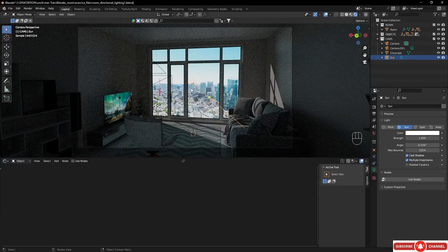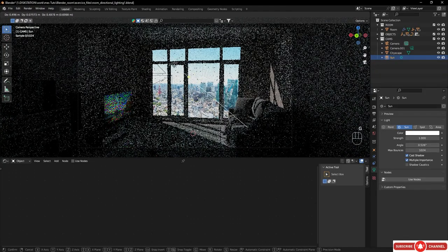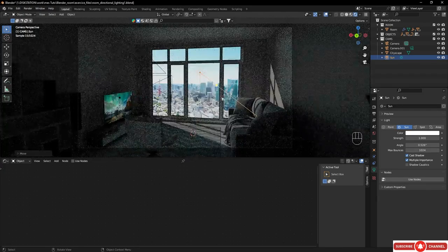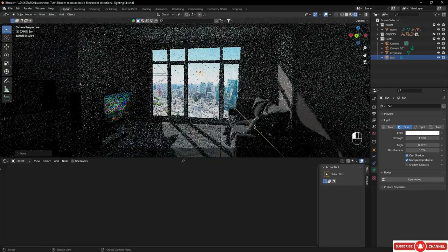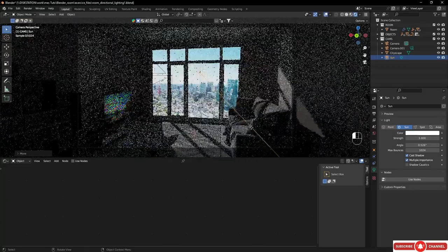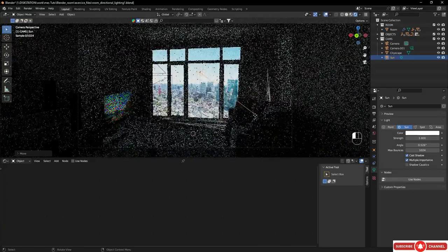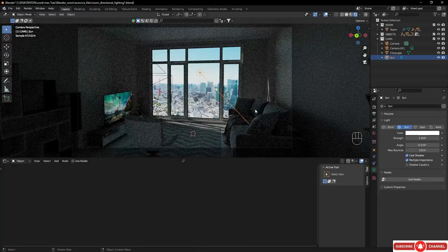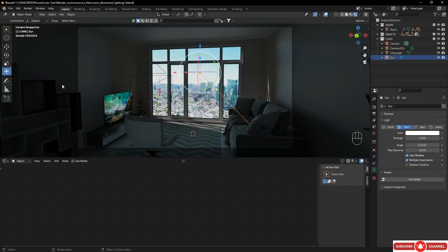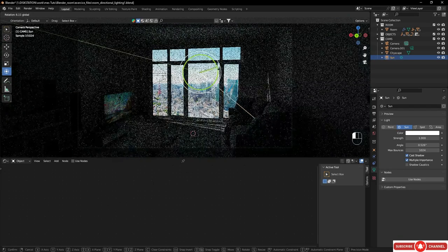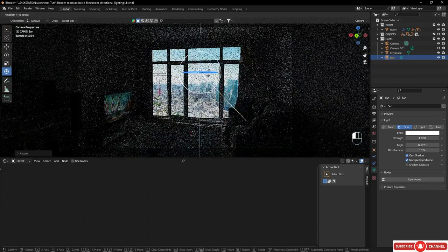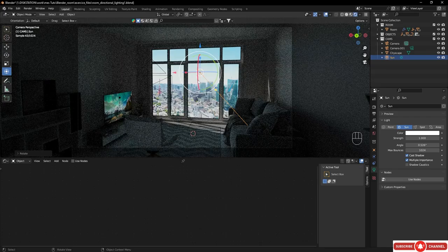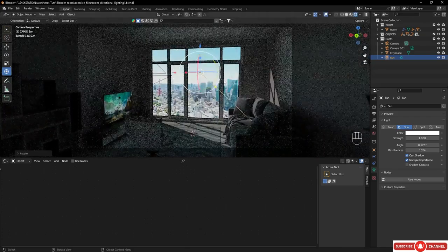Okay, so I can just move now using G our direction light, and you can see it doesn't have any effect on the lighting, so you can put it wherever you want, something like here, for example, and using the yellow dot here, we can very easily orient the lighting. So I would like to have something like that, for example, or we could very well use here our directional tool to orient it further the way I want. So something like that, for example.